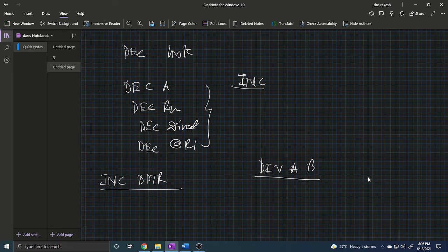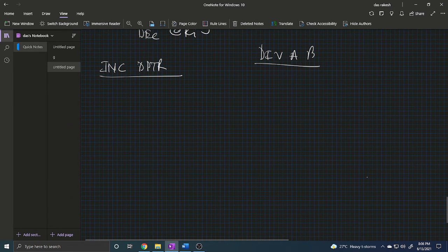So now these are the arithmetic instructions, and another instruction is DA. It's the same as the 8085 DAA, decimal adjust of accumulator after addition. For BCD, this instruction is used after addition of BCD numbers to convert the result back to BCD again. So this is decimal adjust after addition. If we add decimal numbers and want to show the result in decimal form, then we use the decimal adjust.